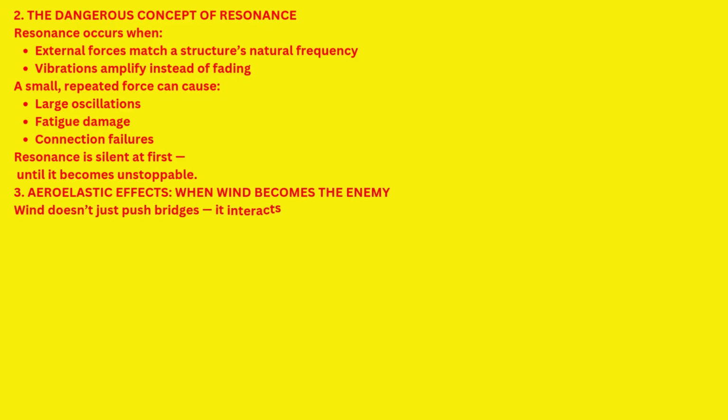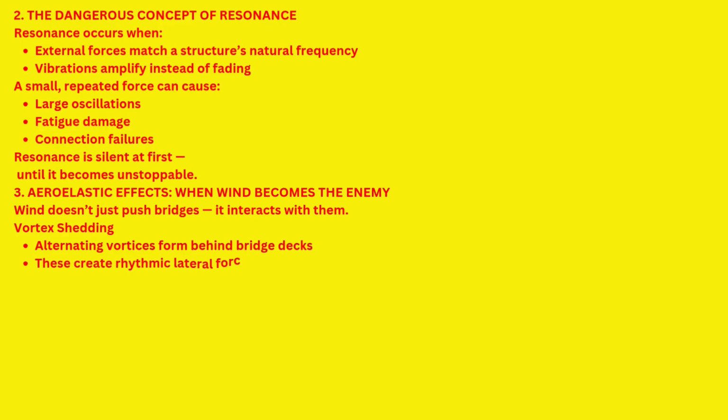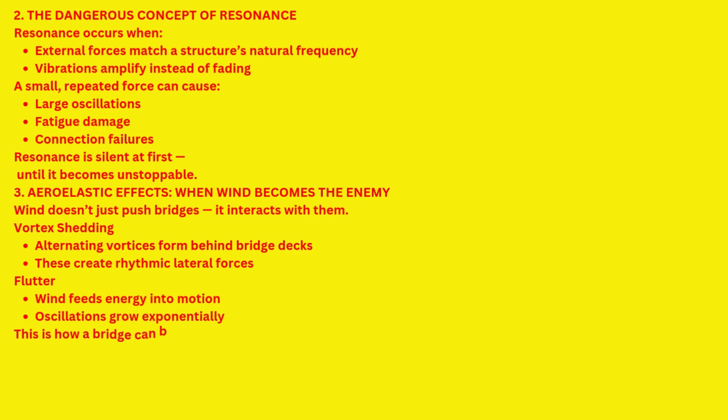3. Aeroelastic effects. When wind becomes the enemy. Wind doesn't just push bridges, it interacts with them. Vortex shedding: alternating vortices form behind bridge decks. These create rhythmic lateral forces. Flutter: wind feeds energy into motion, oscillations grow exponentially. This is how a bridge can be destroyed without extreme wind speeds.